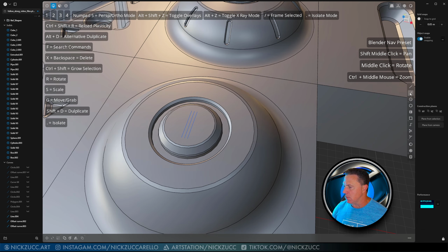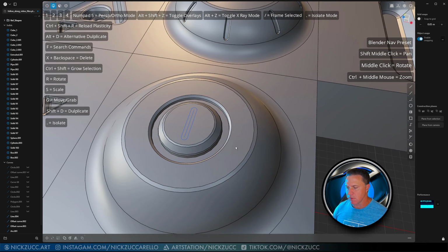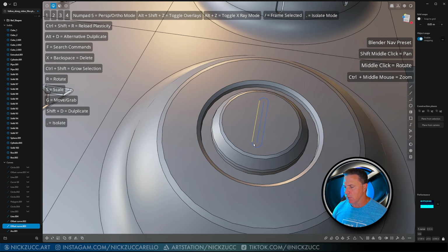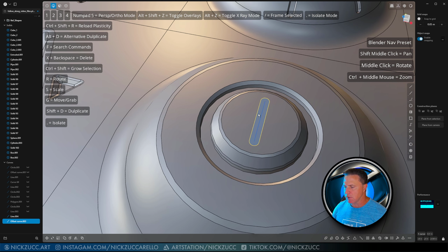If we go back to the curve tool, actually right here, and we do this tangent arc, we can click from this to this right here like that. And if you do Shift R, that will do your last tool that you had. So we can do that just like this. If we want to take those curves and join them together, we can select all the curves, hold down Shift, and just click J to join.